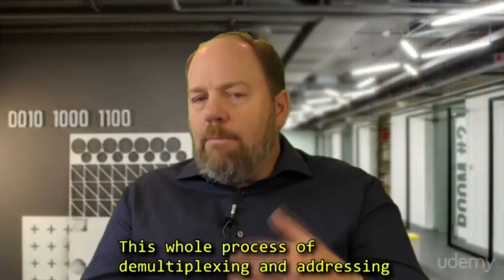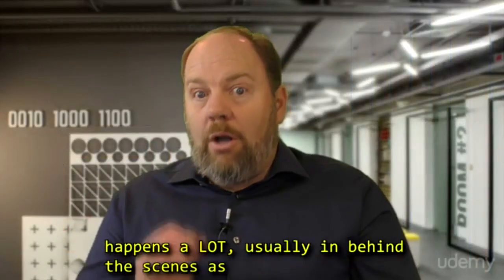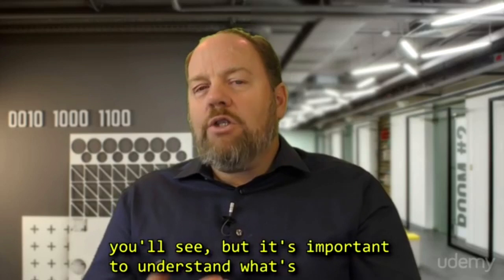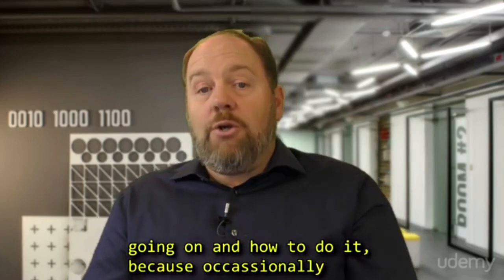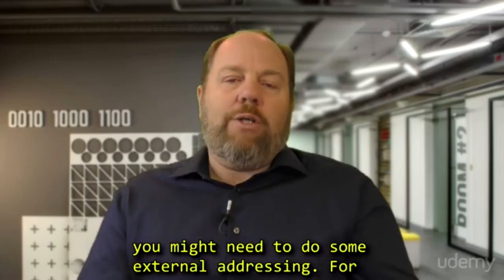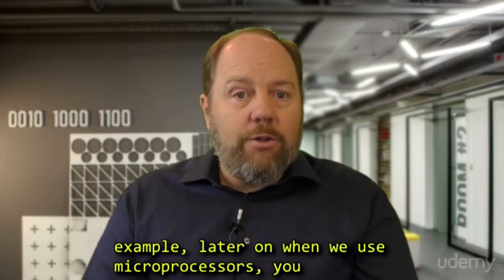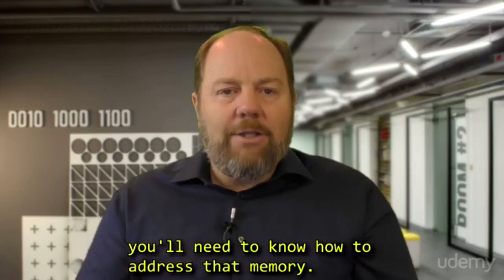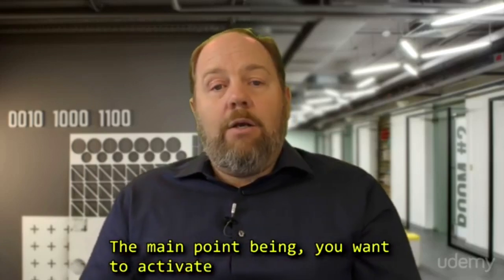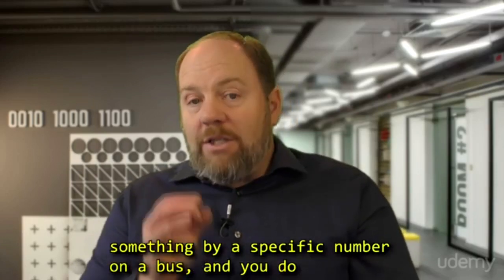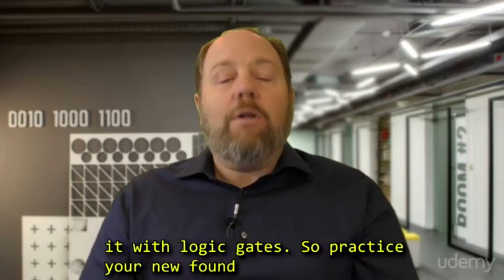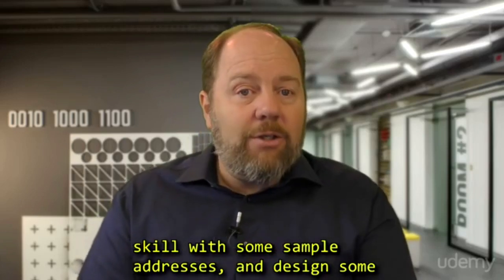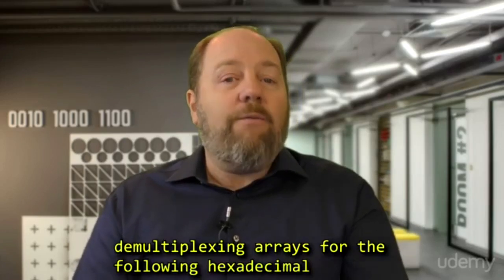This whole process of demultiplexing and addressing happens a lot, usually behind the scenes, as you'll see. But it's important to understand what's going on and how to do it, because occasionally you might need to do some external addressing. For example, later on when we use microprocessors, you might add some external memory of some kind, and you'll need to know how to address that memory. The main point being, you want to activate something by a specific number on a bus, and you do it with logic gates. So practice your newfound skill with some sample addresses and design some demultiplexing arrays for the following